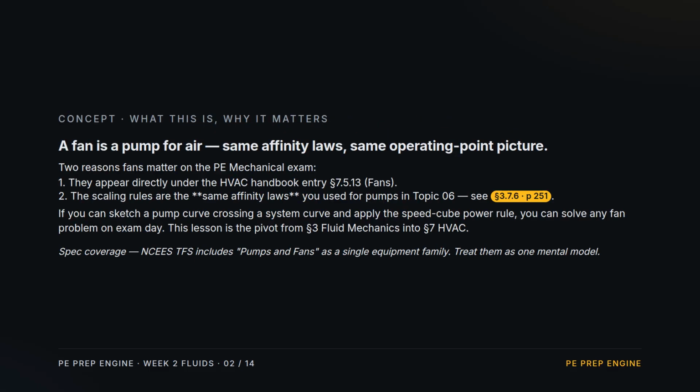2 reasons fans matter. 1. They sit under HVAC in the Handbook. 2. The scaling rules are the same affinity laws you used for pumps in Topic 6. Sketch a pump curve crossing a system curve. Remember, power scales with the cube of speed, and any fan problem falls into the pivot from fluids into HVAC.